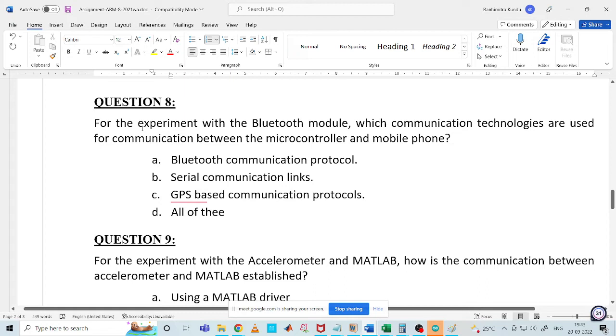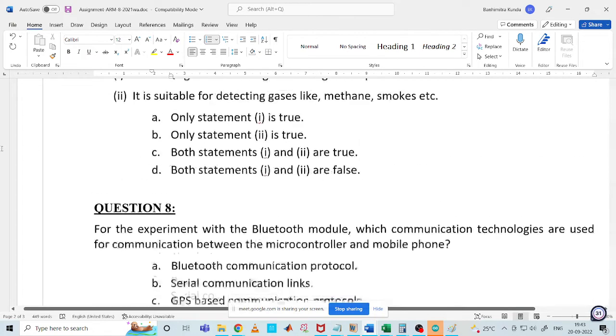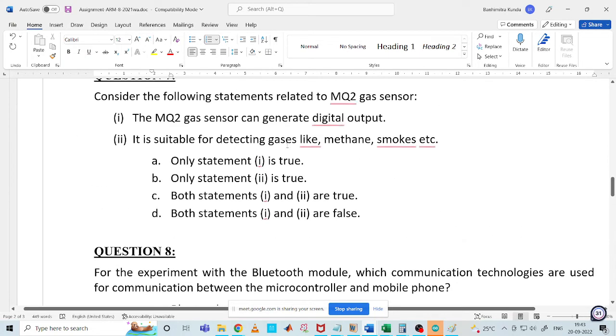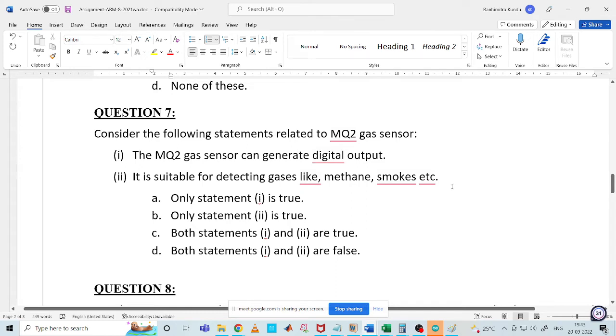Sir, can I ask one question about that? Sure. That is a gas sensor, and there is a module on it that will set the value, and according to that, the digital value will come out. Isn't it like that? Yeah, right. A threshold will be there, which is set through that pot. The pot is there to set the level, and the comparator gives the digital output. Either we can do it that way, or we can detect the analog signal. Yes, absolutely.